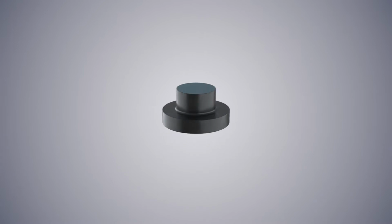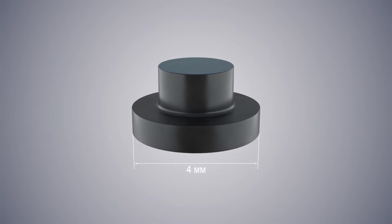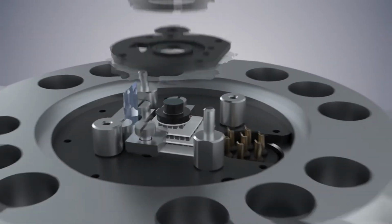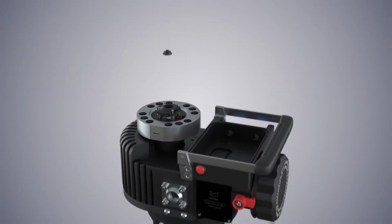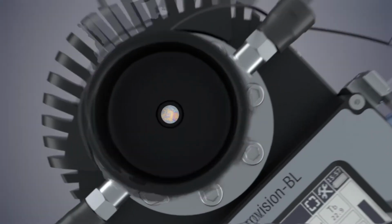The mirror in a Vympel device is a polished silica disc with a diameter of only 4 millimeters. The components of the optical circuit are assembled into a compact measurement cell. For instruments equipped with visual registration, hydrocarbon condensation is observed under vertical lighting.